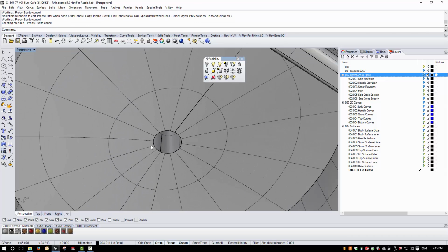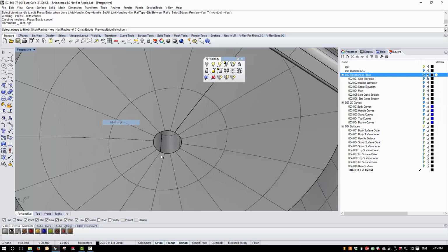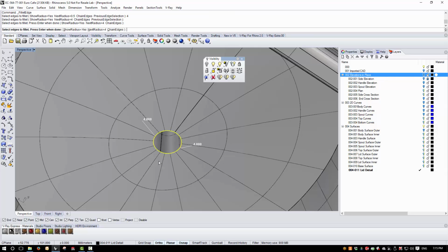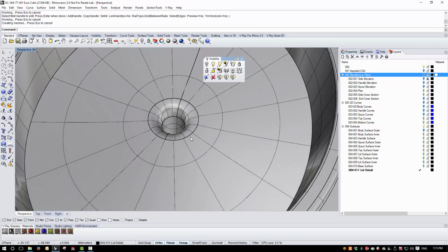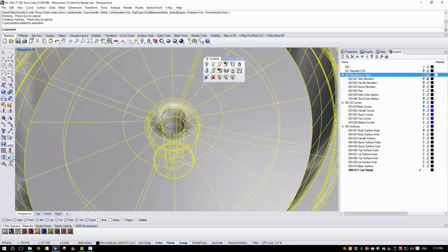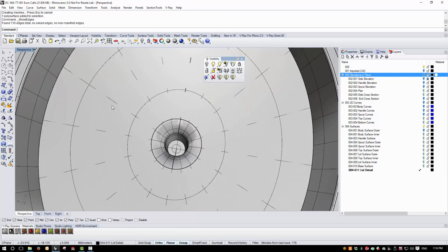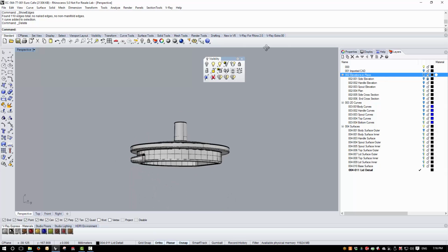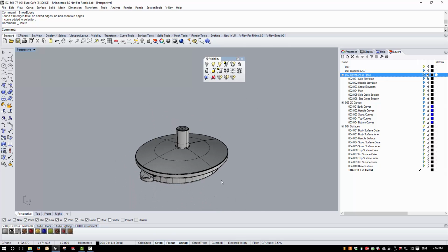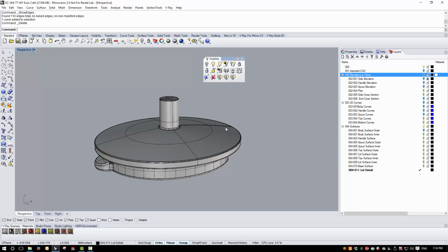And then here we should have the 1 millimeter plus the wall thickness. I'll use a fillet here. Don't need the complexity of a blend. And we just need to make sure that this is going to build correctly here. Okay, that's fine. Just remove that curve. Okay, so that's the lid detail created.